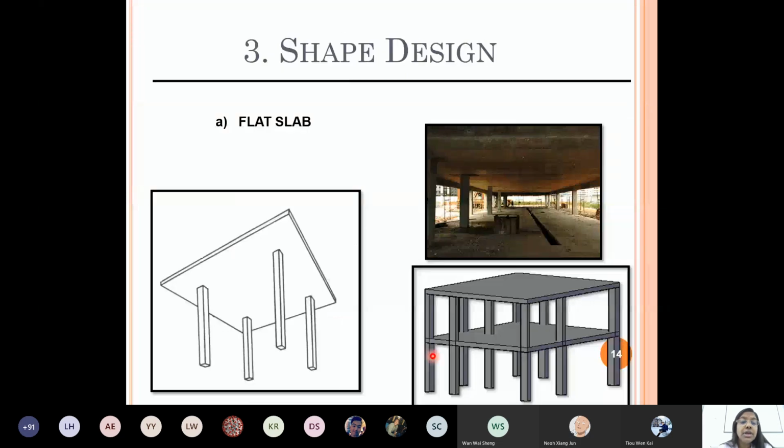Okay, that's important. Whenever I work inside, whenever there's a concrete pour, I have to go around and check all the covers, whether they are in position or not. We place it today, tomorrow the people keep on moving on the reinforcement.